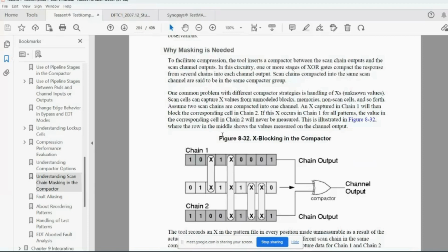In real time, one hot masking helps with tester debug. We purposefully generate one hot patterns before delivering to the tester, so that you have a pattern for each individual compressed chain. So that will become a gold pattern.